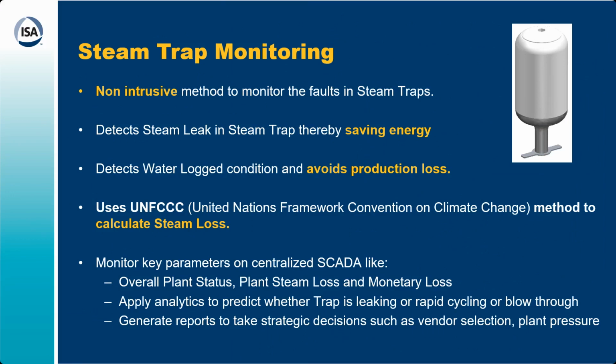You can apply analytics to it. You can predict which type of trap is leaking, whether there is rapid cycling in the steam trap, or whether there is a blow-through condition in the steam trap. All those things you can predict using HART technology, the way you are getting the data.